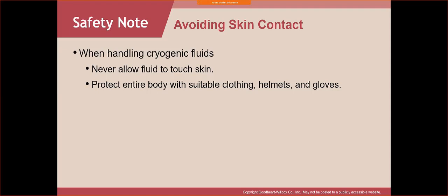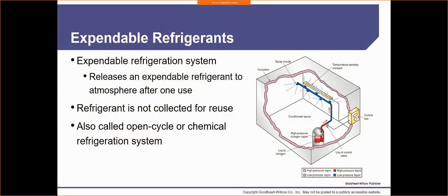Protect your entire body with suitable clothing, helmets, and gloves. Yet again, these fluids are extremely cold, and so any of that stuff getting in touch with your skin or your eyes is going to burn it or destroy it. So we're talking about, what's the term that I'm looking for? Frost. Either way, it's going to freeze your stuff, and you don't want that.